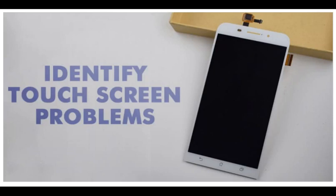A projected capacitive touch screen is composed of a sheet of glass with embedded transparent electrode films and an IC chip. This creates a 3-dimensional electrostatic field. Therefore, when a finger comes into contact with the screen, the ratios of the electrical currents change and the computer is able to detect the touch points. All our PCAP touch screens feature a 0-bezel enclosure.